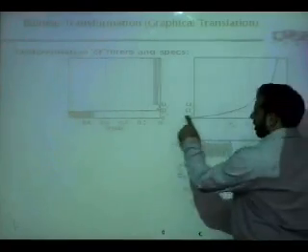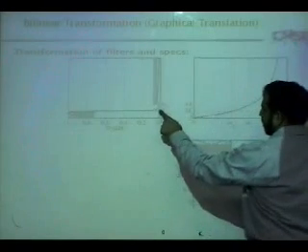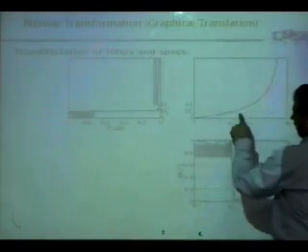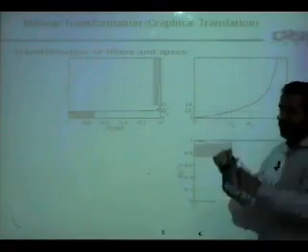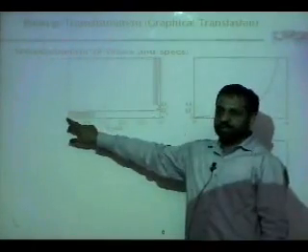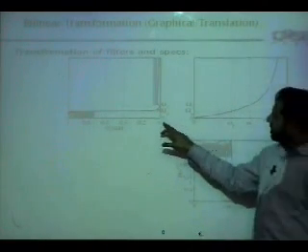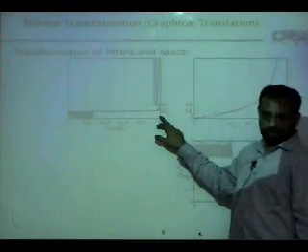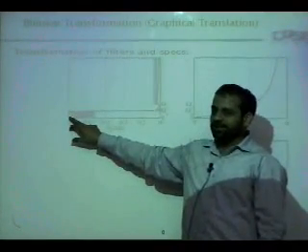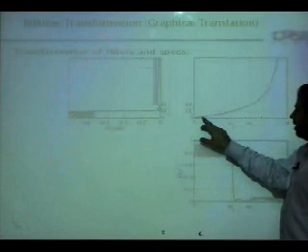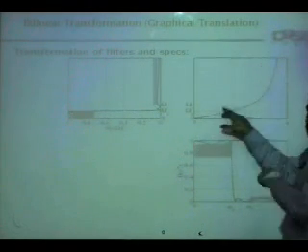But because of this, if it meets specifications here, it is guaranteed that it will also meet specifications here, because you are taking a value and just plotting it here: taking an omega p, converting it into small omega p and plotting. This is how you plot. You take the value at 0 as 1, and in small omega the value at 0 is 1, for example. Now you take another value at capital omega p, let's say 0.9. You take this capital omega and convert it into small omega. How? Using that formula, which is basically this curve.